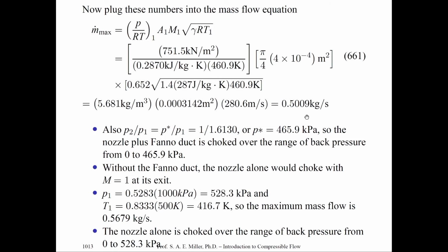Also, of course, the flow will be choked for other ranges of pressures. Of course, because of raising the pressures, it won't matter. The flow is choked and remains choked. And you can't change the mass flow rate by increasing the pressure ratio.